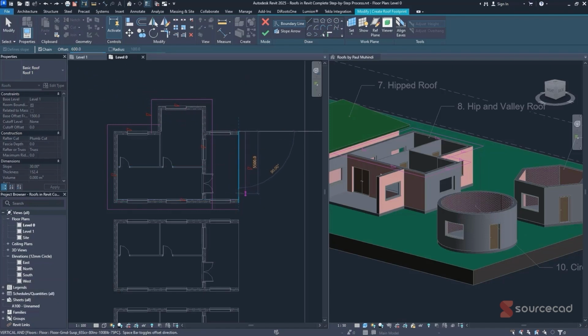And if you want it to be toggled to the other side, or flipped to the other side, all that you have to do is hit the spacebar on your keyboard, and it's going to flip over. So I'll hit that so that we place it there. And we obviously need another line here. So I'll select there, and then I'll use my Trim/Extend. So I'll select that, and then select this one, and then I'll select that, then I'll select that and that. And just like that, let's also clean around here. So I'll select this side and that side, so that we'll be left with that.